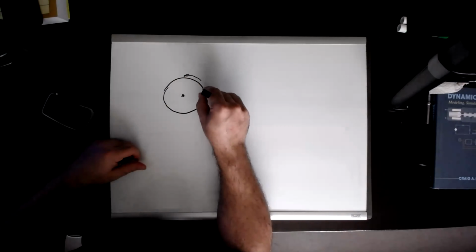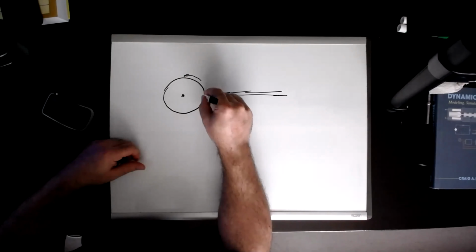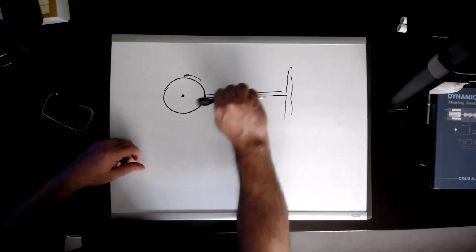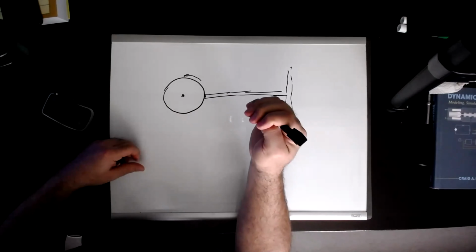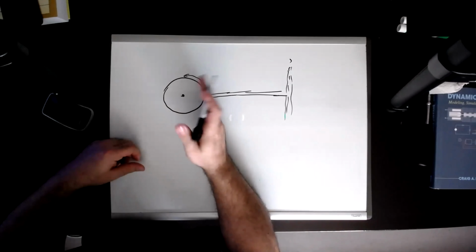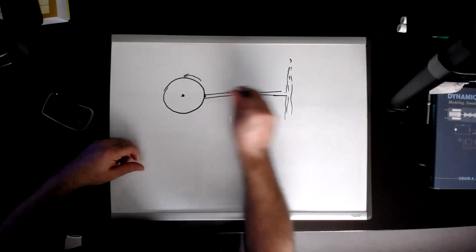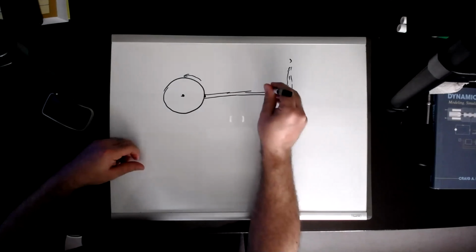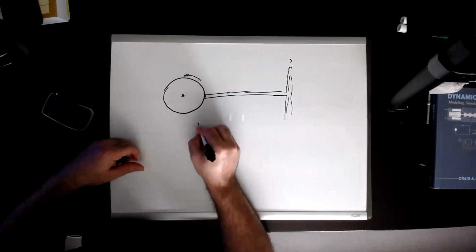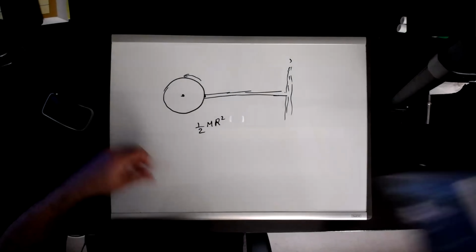But if I have something very far away attached to that disk, and I want to rotate it around this axis, it would be more moment. So the axis of rotation is important. You will see the parallel axis theorem: m times this distance d squared plus I around this. So for I of this, it is 1/2 of mr squared. You can look it up from the back of the book.